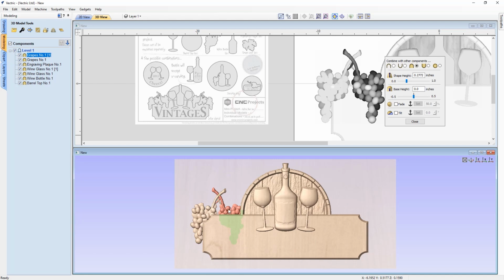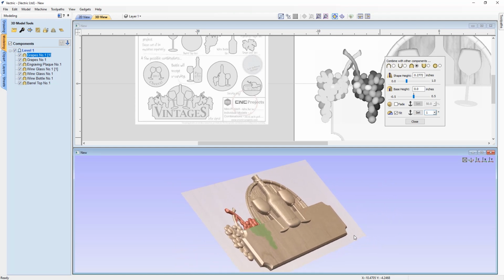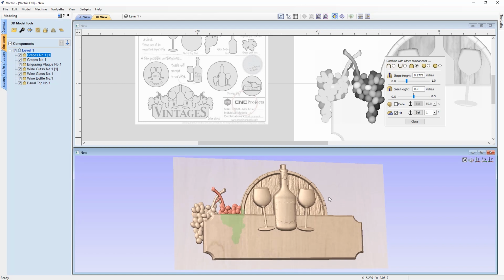So to do that, I'm going to simply select this component and you'll see that now my floating properties dialog box has been populated with this information from this particular piece of clip art. I'm going to tilt it again. Set my 2 anchor points. This time I'm going to set one down here, my other one here. That way I want it to angle from here to there. That's my axis of rotation. And so then I can go ahead and change that to be 1 degree. Press the space bar and you'll see now it's poked up proud of that other stem and it looks pretty nice in the end. I like that.